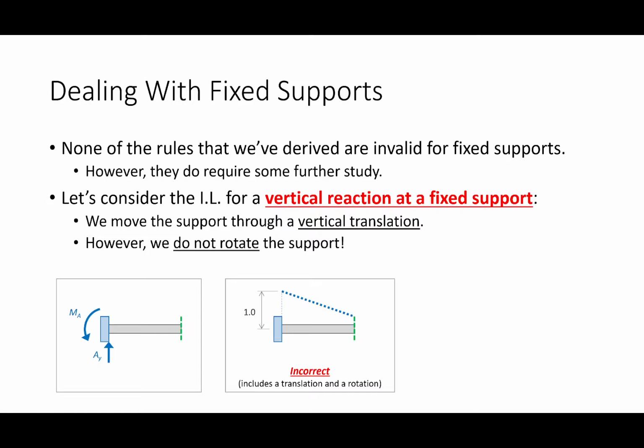Going like that. And let's say that's my support condition. I know it's a little bit of an odd support condition, but let's just say that that is my new support condition. Does this connection for this beam, so we're talking about this beam right here, does this connection resist loads left to right? Like, can I yank it this way, and will this support condition resist those loads? I would say yes, right? Like, if I take it and I pull it, the bolts are going to keep it there, okay?